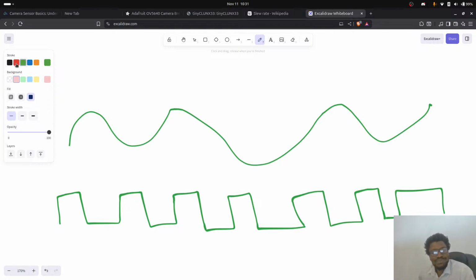So here's the thing: in SDR, or single data rate, you would only sample the data at this point. Okay, so let's pick the leading edge. You'd only sample the data at this point. So what data would you get? There will be no data here. This would be the data. And then what would you get here? You would get this. This is a sample. This is the sample, and this is the sample, and this is a sample. So this is your real world signal.